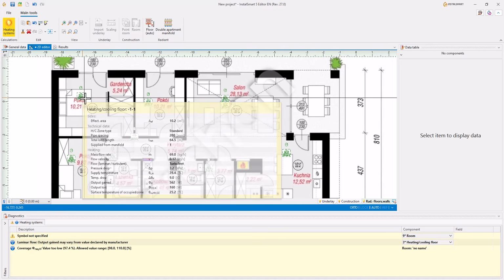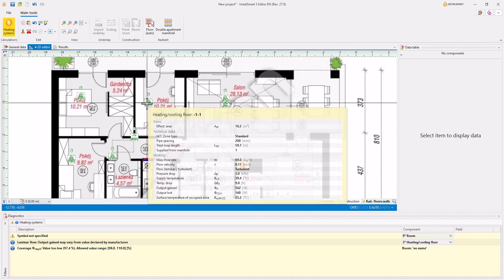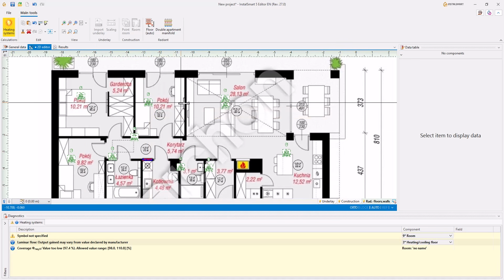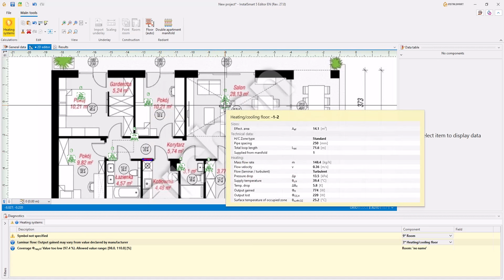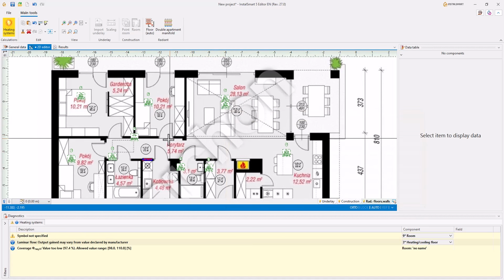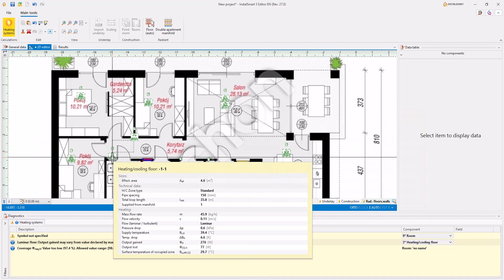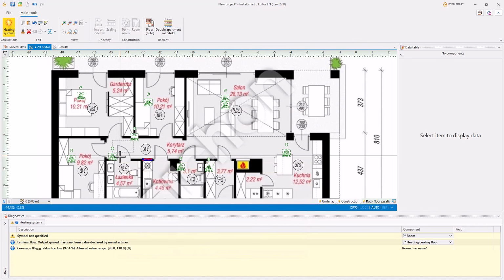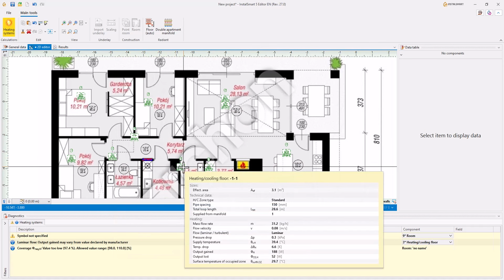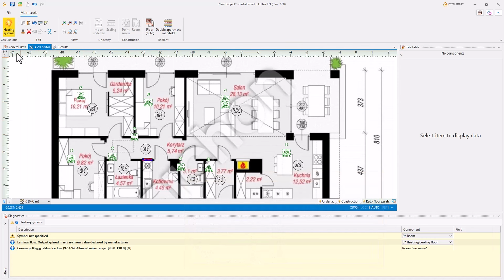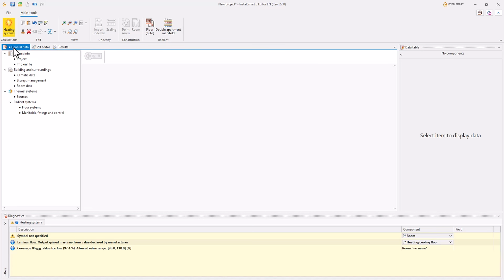In single-family homes, the pipe spacing for underfloor heating is typically set between 10 cm and 20 cm. A spacing of 10 to 15 cm is used in rooms that require higher temperatures, such as bathrooms. In warmer regions, these values might be larger, whereas in colder regions, smaller spacings can be used to ensure more effective heating. To change the spacing from the standard range, you can go to the General Data section